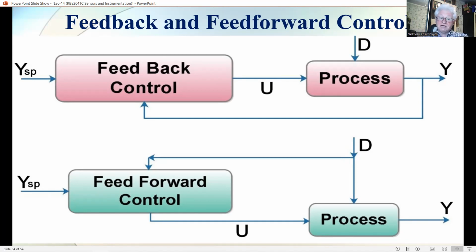Under these circumstances, a measurement system is not needed, or at least not needed for feedback into the control. And thus, we have an open loop control system. In open loop control, we do not use current information on system response to determine the control signal.